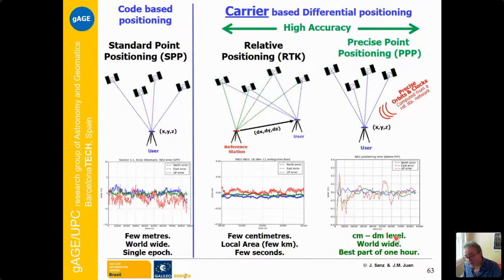In PPP, this is worldwide, like in code-based positioning, but it takes longer to converge. The best part of 1 hour, and we have centimeter to decimeter level.